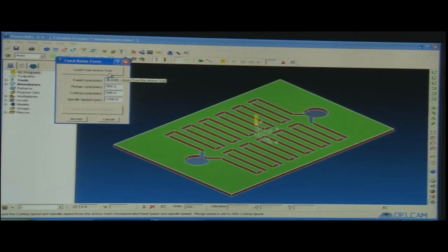Then, okay, we can now select the feed rates. Now, load from active tool. Active tool means when the tool is actually working and the machining is happening, what is the load that the tool gives to the workpiece; those values can be put here. We skipped the plunge options before, because I will just fix that here. Now, how the tool enters the job for machining.